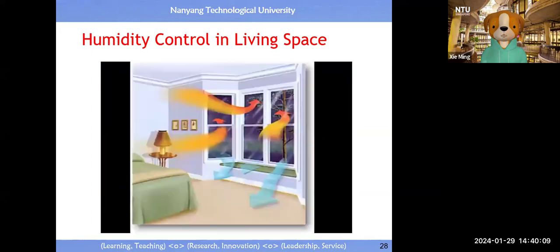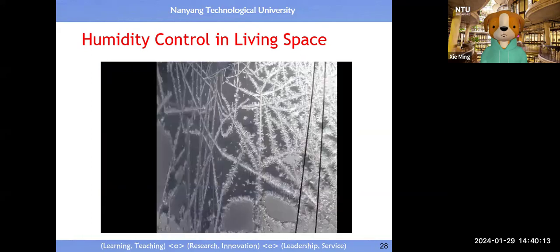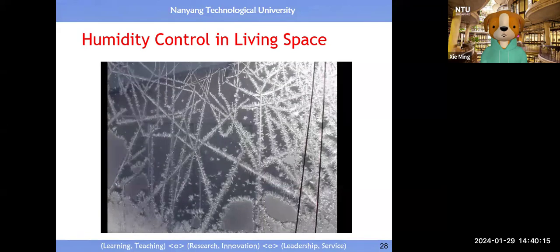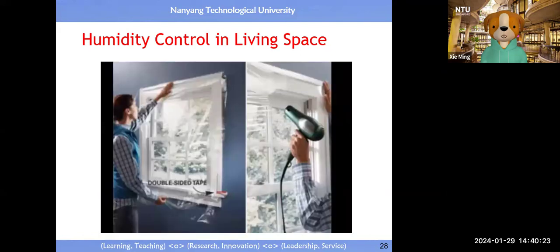High humidity in some rooms can be problematic. Kitchen, bathroom, and bedroom windows can collect moisture or frost as the glass cools below dew point. Consider upgrading to thermally efficient windows in these rooms or cover the glass with plastic to prevent condensation from forming. This prevents the moist indoor air from contacting the cold glass. Ensure that the plastic is well sealed for the plastic barrier to work properly.